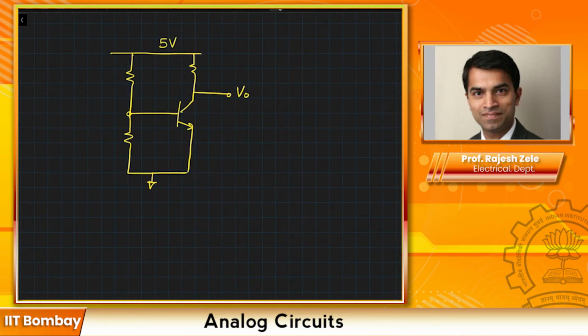One point I would like you to know is that we cannot just connect an AC voltage source right at this point, V in AC. The reason is, if you apply an AC voltage source like this, then the DC value at this node will become equal to 0, and the transistor will cease to operate in the region that we want, and it will be cut off.